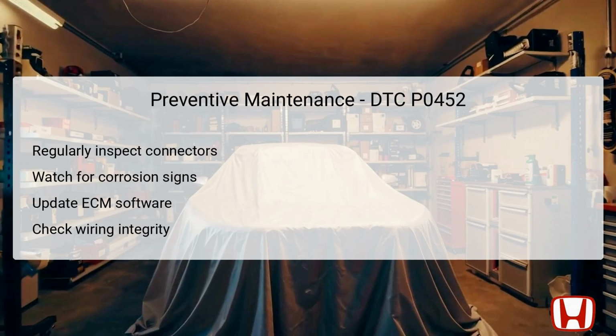Keeping the ECM software updated ensures that the vehicle benefits from improvements and bug fixes provided by the manufacturer, which can optimize sensor performance. Lastly, routinely checking the integrity of the wiring harnesses can prevent shorts and opens caused by physical damage over time. Employing these preventive measures can enhance vehicle performance and prolong the lifespan of critical components.